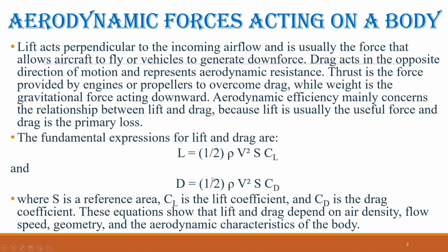Drag equals 1/2 multiplied by air density multiplied by the square of flow velocity multiplied by reference area multiplied by drag coefficient, where S is the reference area, CL is the lift coefficient, and CD is the drag coefficient. These equations show that lift and drag depend on air density, flow speed, geometry, and the aerodynamic characteristics of the body.